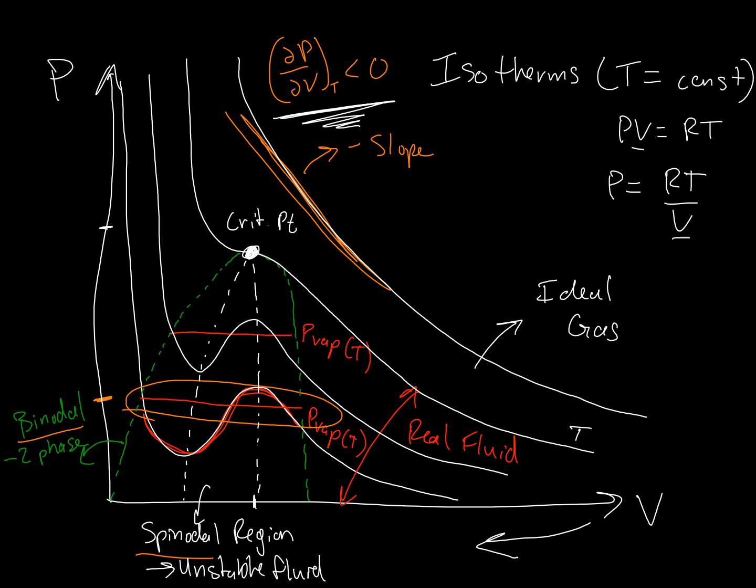And then with mixing rules, we can use a cubic equation of state to repeat the process for a multi-component system. So we can do flash calculations, distillation, solid-liquid equilibrium, vapor-liquid equilibrium. Any type of equilibrium can be made with the right particular kind of equation.